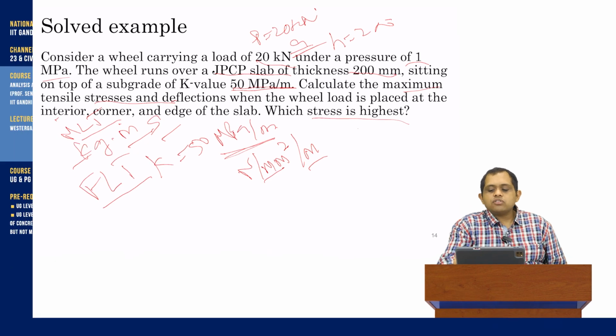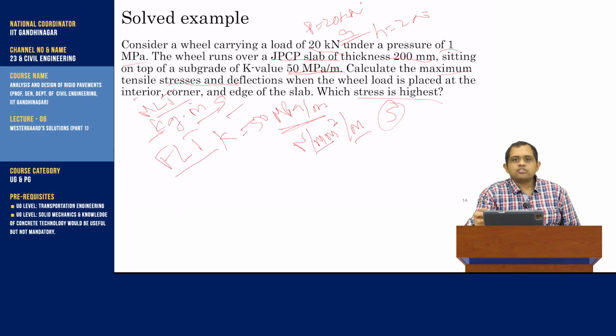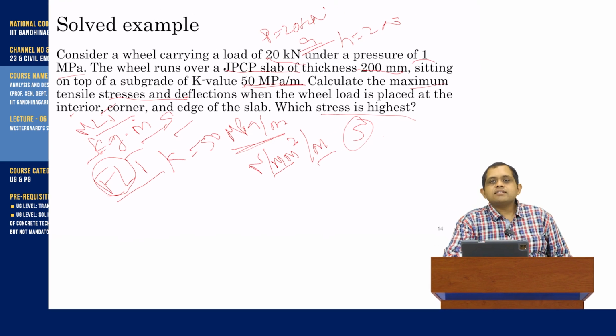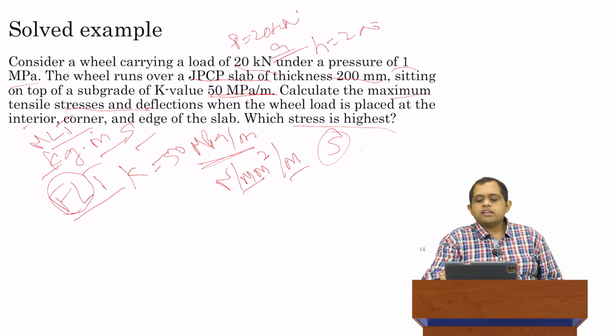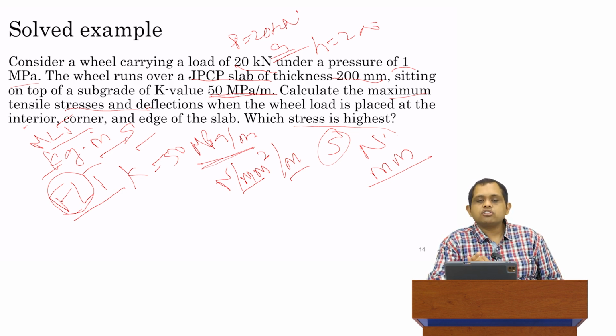In this case, time is going to be in seconds, but it doesn't actually matter because our solution is static, so we don't have any time units anywhere in our solutions. We have to choose units of force and units of length. It's an arbitrary choice. You can choose whatever units you want. But perhaps the easiest set of units to use for all problems is force in newtons and length in millimeters. Note our units, the actual units of our problem, don't follow this convention, and the units which I've given here are actually the conventional units which are used.